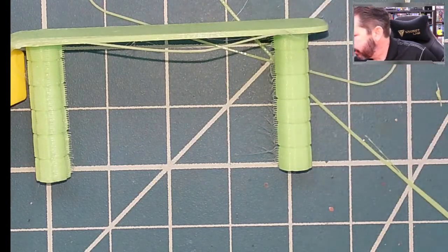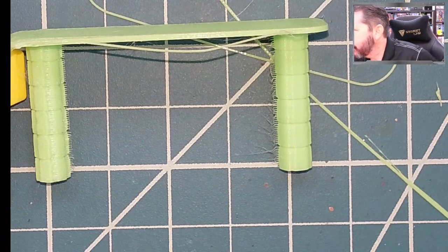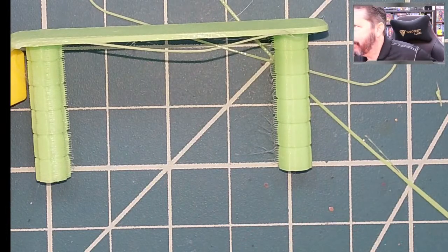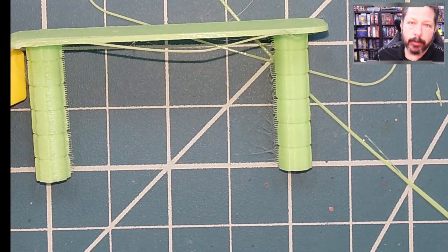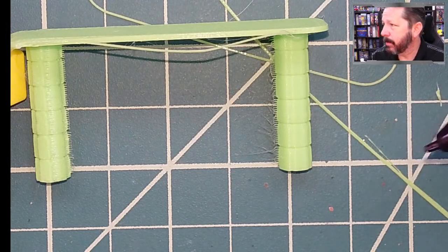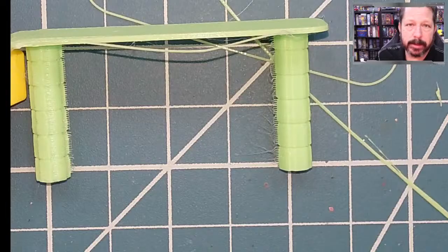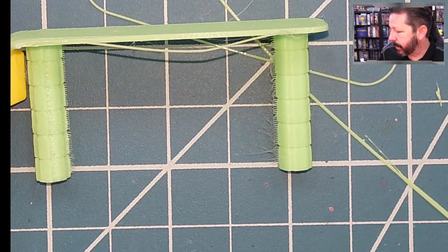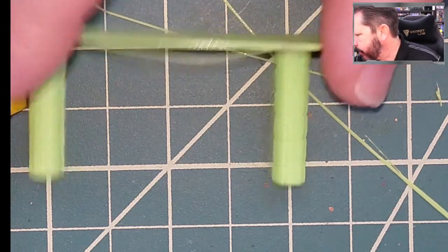Each one of those squares is 1/2 inch, so we're really zoomed in pretty close. Probably my next tuning thing would be, let's see how Z-Hop works on this, and the higher settings. So maybe 1 millimeter. The speeds don't seem to make a lot of difference, so maybe the 1 millimeter, but 30 millimeters per second, and see how that goes.